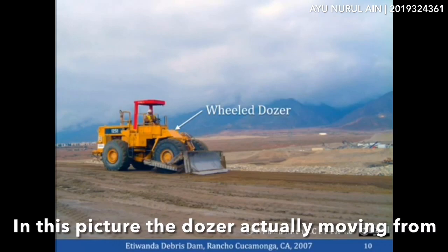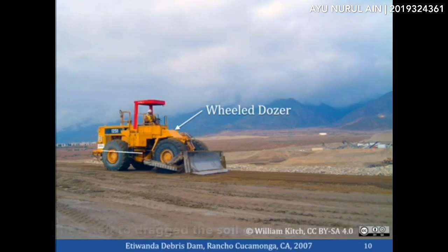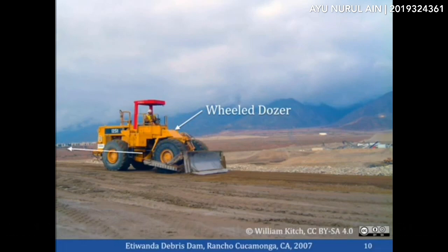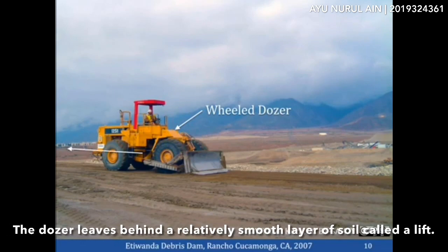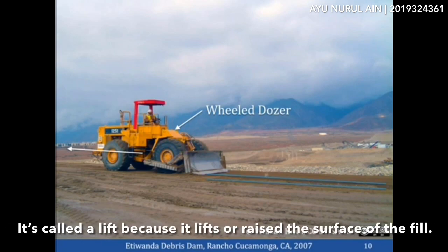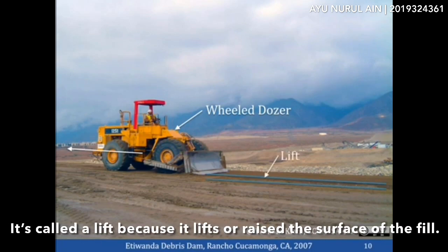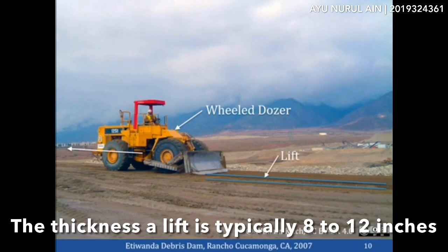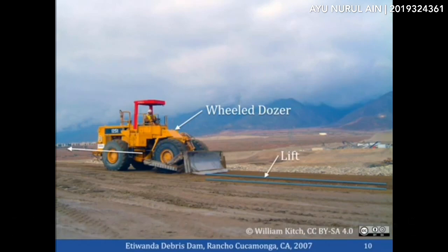In this picture, the dozer is moving from right to left to drag the soil on the back side of its blade. The dozer leaves behind a relatively smooth layer of soil called a lift. It's called a lift because it raises the surface of the field. The thickness of a lift is typically 8 to 12 inches or 20 to 30 centimeters.